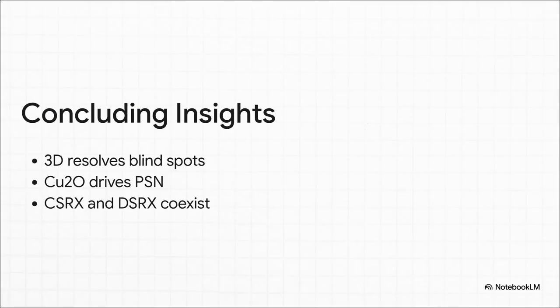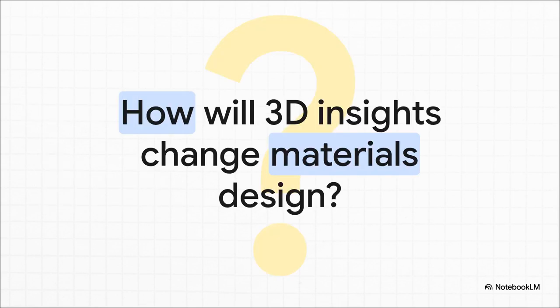It's spot on. So, to summarize our whole synthesis framework today, non-deformable catalysts force extreme localized strain, and that leads to a concurrent, highly heterogeneous room temperature self-annealing response. Coarse particles, specifically those larger than 1.5 micrometers, are highly efficient for this. We now know definitively that room temperature self-annealing is not some monolithic event. Actually, CSRX and DSRX operate concurrently side by side, generating a really complex matrix of strain-free grains alongside active subgrain recovery zones. I want to leave you with this final, provocative thought to spark your future academic exploration.